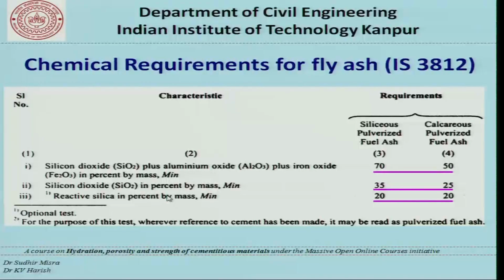fly ash particles. In the last lecture we have clearly seen that if the particle sizes are lower than 10 micron, then that will initiate the pozzolanic reaction, and we tend to get strength at early periods. But if the particle sizes are between 10 to 45, then they usually take more time to react with calcium hydroxide formed from cement hydration, and that will lead to later age strength. But if it is greater than 45, they basically do not take part in the reaction.